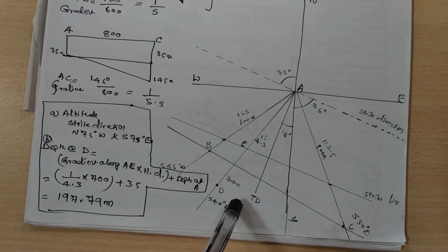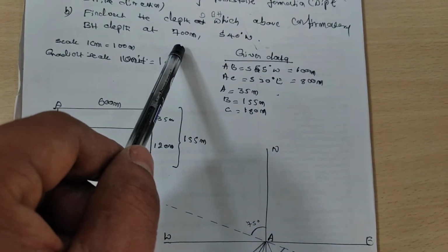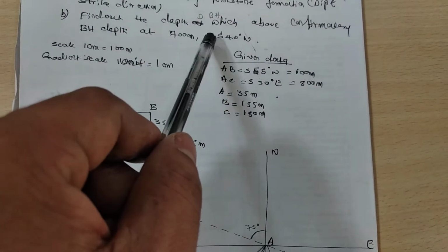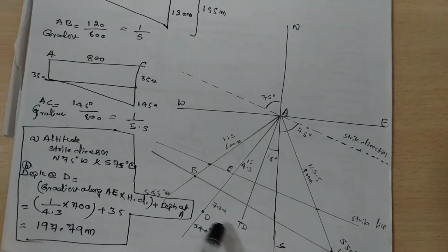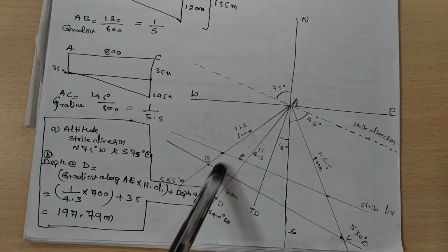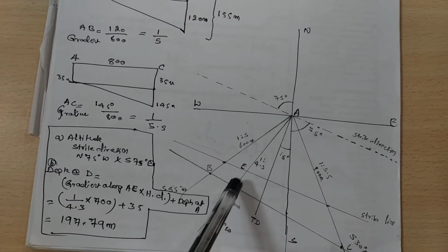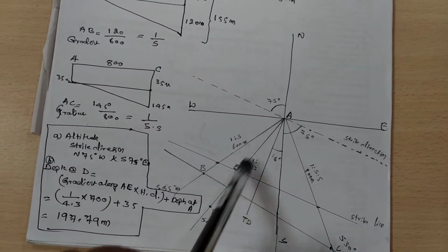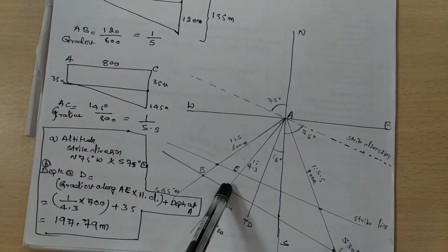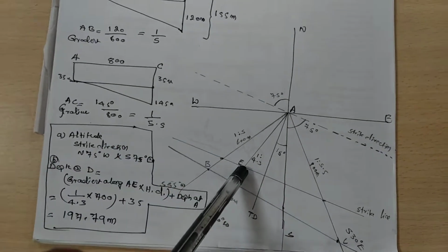So we need to calculate another, fourth borehole, that's called borehole D depth. The confirmatory borehole, we drilled it here. This is a confirmatory borehole. We got 700 meter horizontal distance, and south 40 degree west. South 40 degree west here, measure it and mark it, and mark with the 700 meters here. So here we got another point that's called E point, that is called our gradient of AE. That will be 4.3 centimeter from here to here.